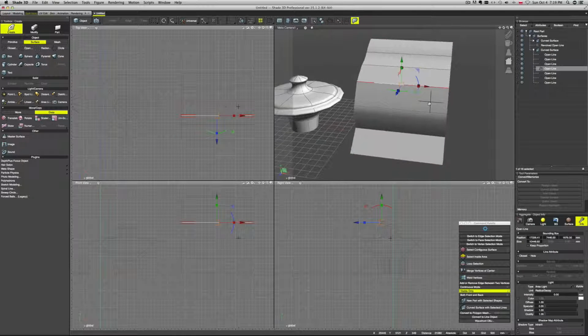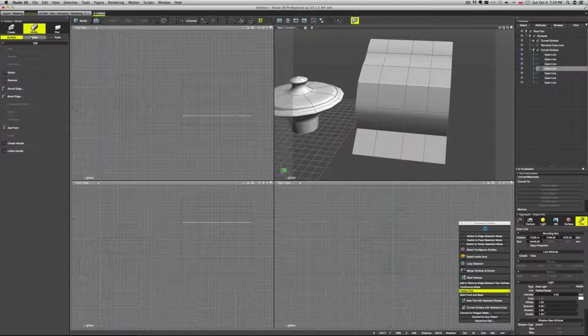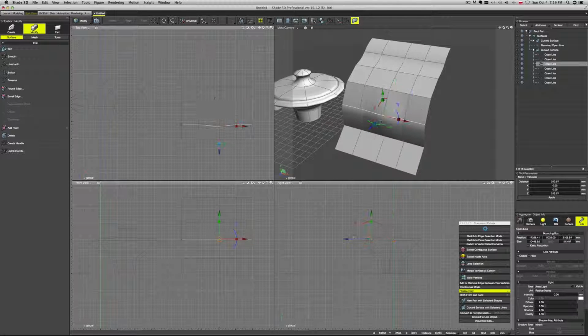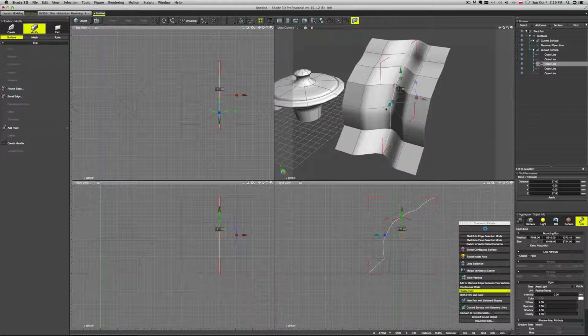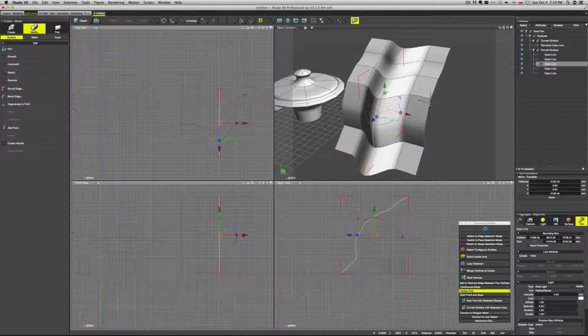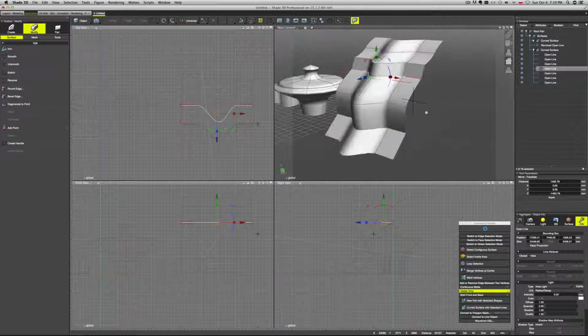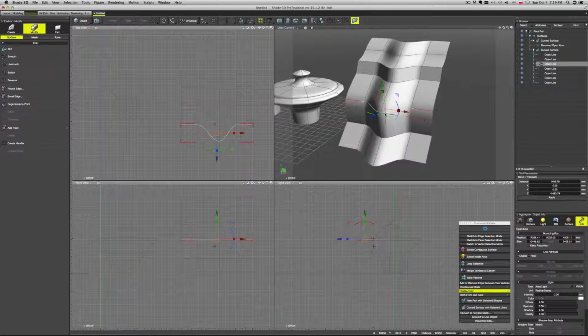And now let's modify it a little bit. Let's add lines. Basically by going to modify surface add point, I have it as a shortcut. I'm just pressing the U key and it allows me to add additional points. You just click and drag across one of the lines and it will automatically add another loop. That way you can add more lines to your object, to your surface, and start modifying and tweaking it.